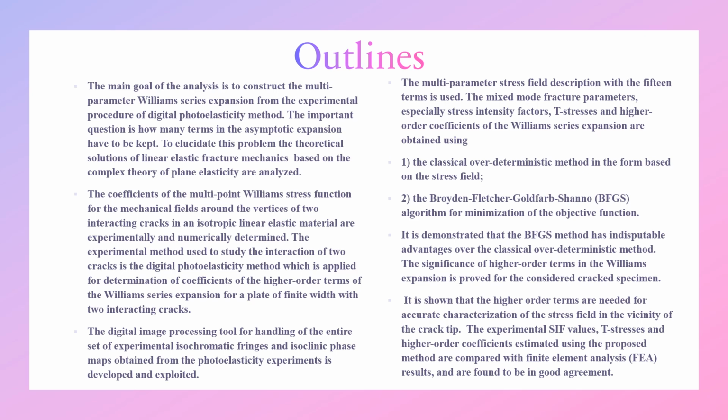The digital image processing tool for handling the entire set of experimental isochromatic fringes and isoclinic phase maps obtained from the photoelasticity experiments is developed and used. The multi-parameter stress field description with 15 terms is used.